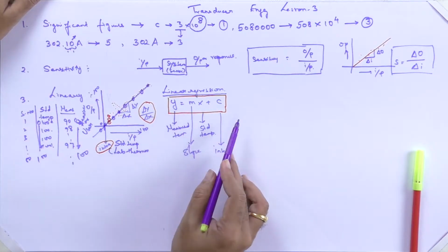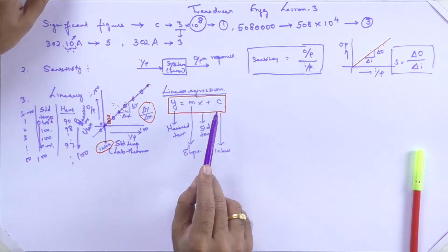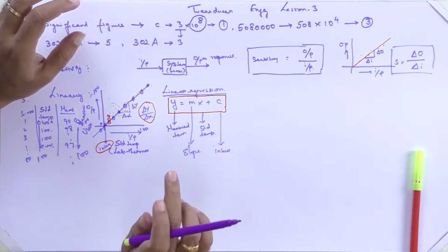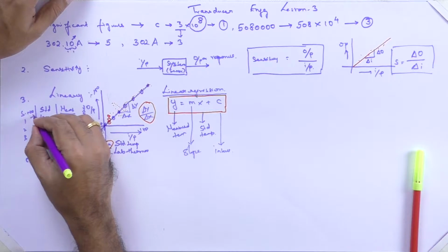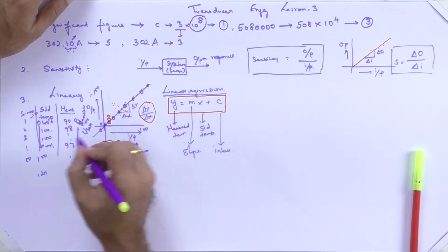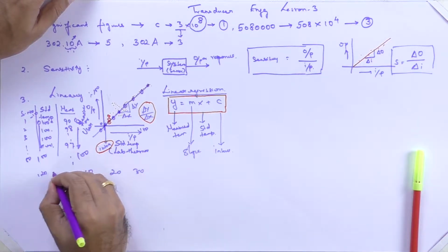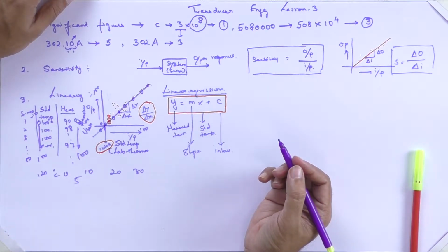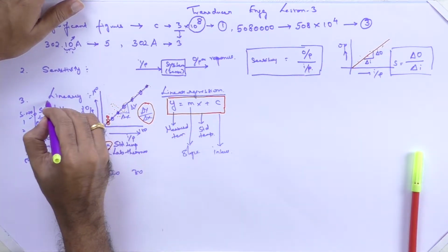We are now able to frame an equation directly from the measured values, y = mx + c, and this equation is a very powerful way to calibrate your sensor. Now you have data only from 0 to 100, but when you want values such as -10 or above 100, like 120, you can simply substitute them into this equation. Or in between values, if you are taking readings at 0, 10, 20, 30 degrees centigrade but want 5 degrees centigrade, you can put 5 into this equation and obtain the output. So this is to check the linearity and also to calibrate the system.